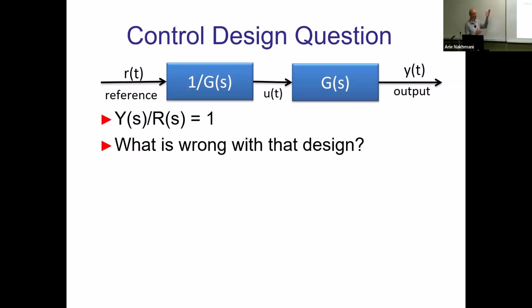What if the system is unstable? How about an unstable system, and you're putting it in open loop. It will stay unstable. Why should it become stable if you have something unstable? More than that, if you have unstable zeros in G(s), and then you're inverting it, they become poles.